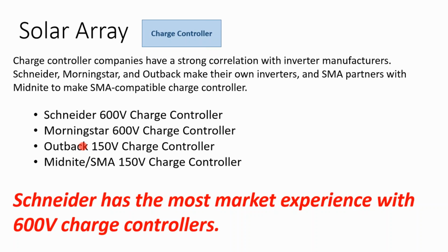I'm doing a 22 kilowatt array that has 110 solar modules on it. I don't want to have 30 circuits up on my rooftop. That's just too much wiring. I'm used to doing solar with 600 volt circuits of at least 10 modules per circuit.